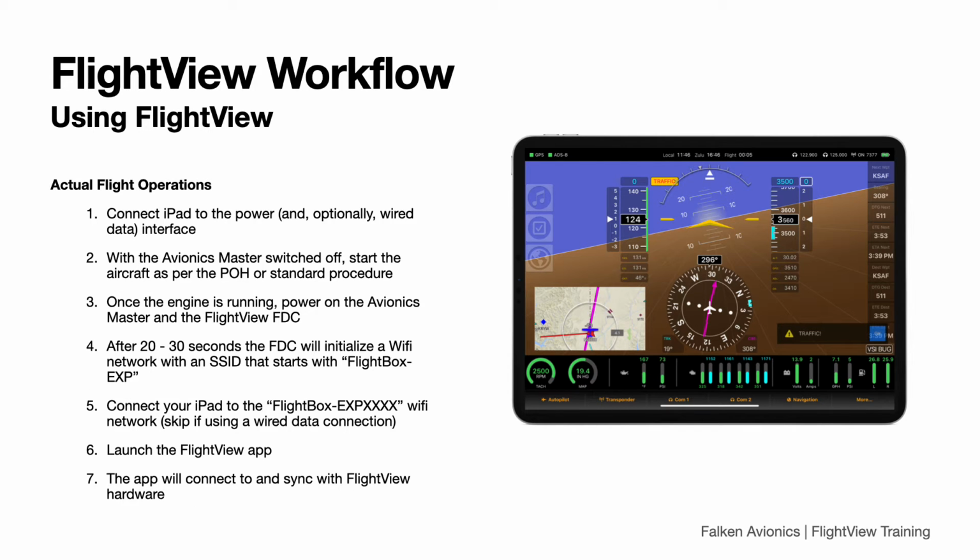The process for starting up is about the same in an actual airplane. Start by inserting your iPad into whatever mount you've opted to use and connect it up to the charger. Make sure the avionics master is switched off and then follow the standard procedure to start your engine. This reduces the chance of a spike or a brownout causing problems with your avionics. Once the engine is running, turn on the avionics master and boot up the FlightView system.